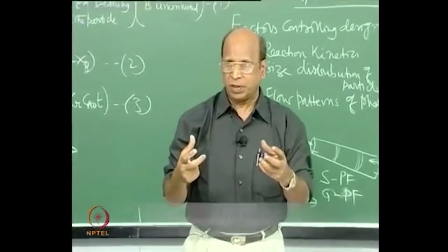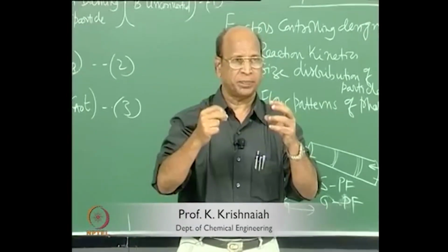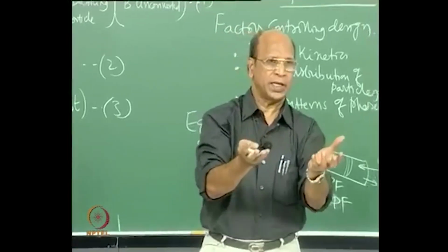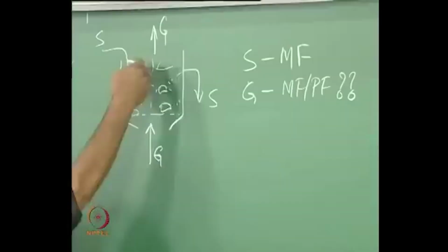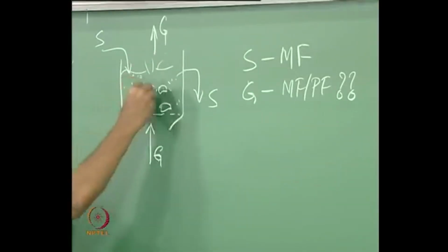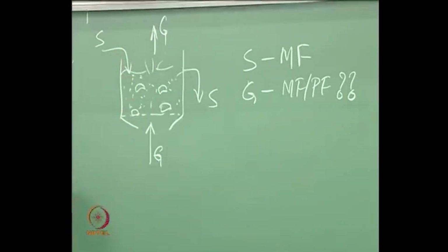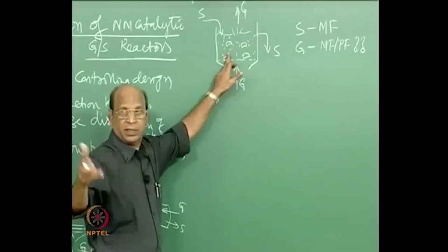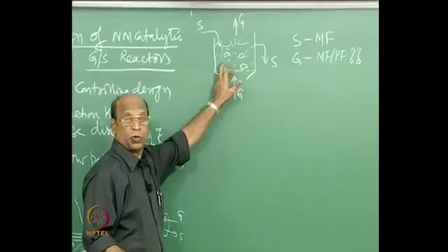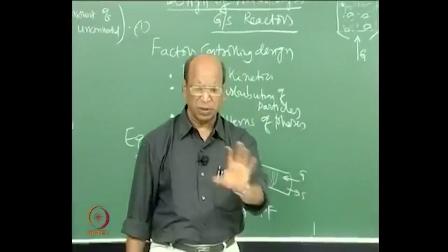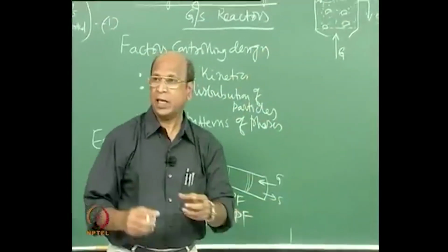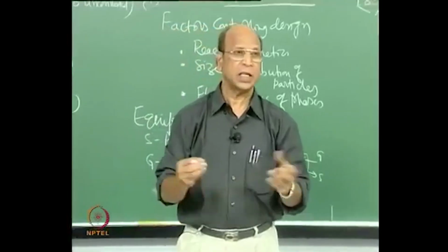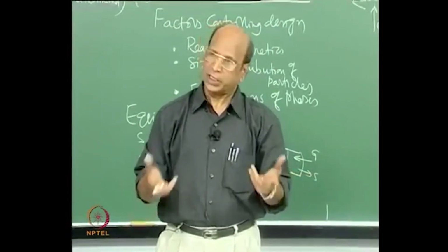because in fluidized bed all these particles are held up or floating in gas, and then these bubbles are there where they go vigorously up and then break. When they are breaking, solids can jump up and then again fall. So when they are falling, they will go anywhere, and that is how you will have almost perfect mixing. RTD also you can do that and then find out it is almost equivalent to plug flow, mixed flow. Okay. So that means a particle in the fluidized bed can move anywhere, anytime. That is the definition of perfect mixing, and that is true in a fluidized bed.